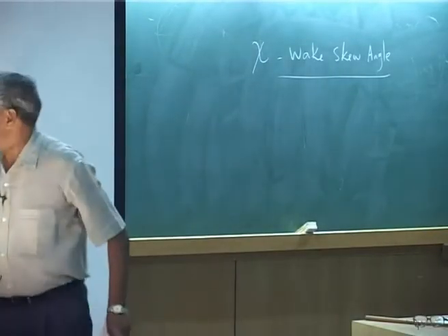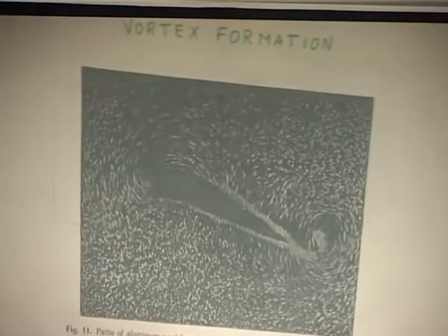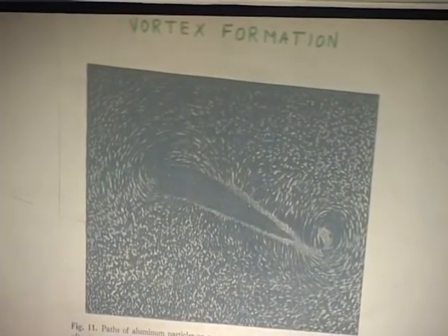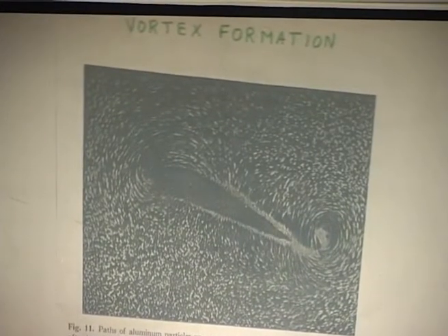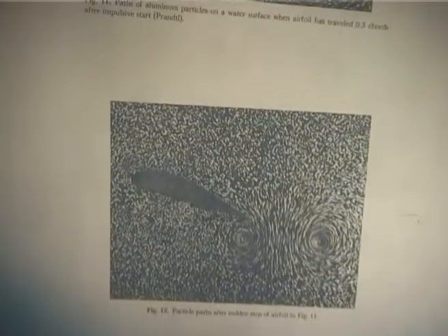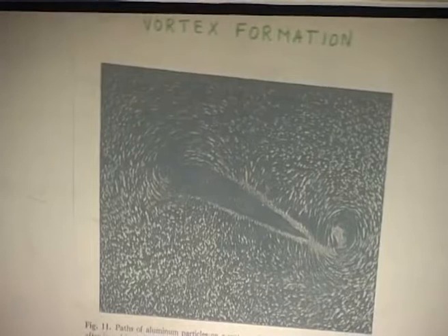See, this is when you start an aerofoil, because there is no lift. When you start means what? Your velocity is increasing. That is why the vortex theory, that lifting line theory which you call it, is a very, very powerful technique, because as an observation, when the aerofoil starts from rest, there is no circulation. That is why we call it irrotational field. Those of you who are familiar with fluid mechanics, I am just saying irrotational fluid.